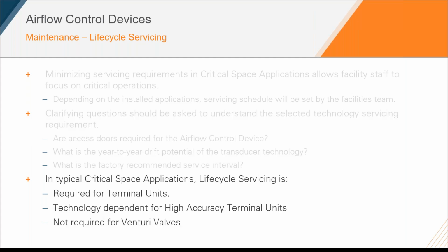So in a very generic critical space application, I'll summarize a little bit about the life cycle servicing required for the terminal unit, high accuracy terminal unit, and the venturi valve. Typically, because your terminal unit has the sensor ports facing directly in the airstream, you will see a lot more servicing required for that legacy terminal unit.